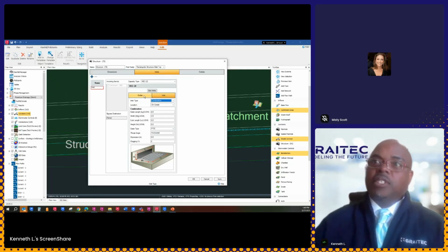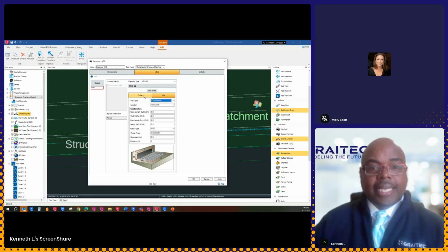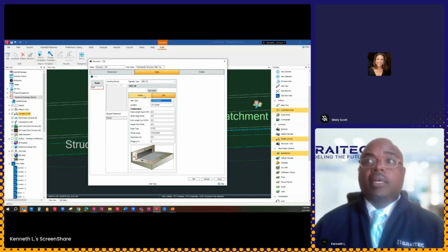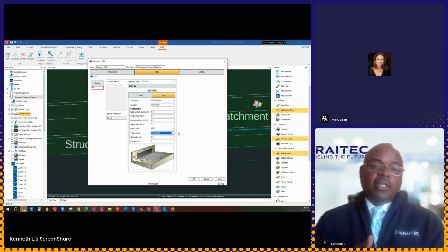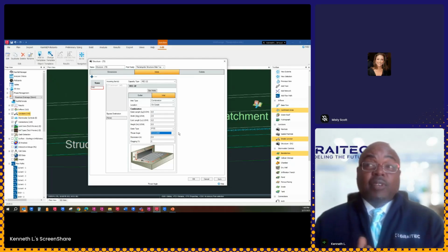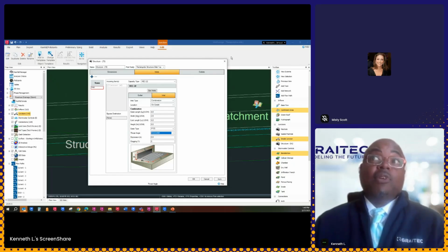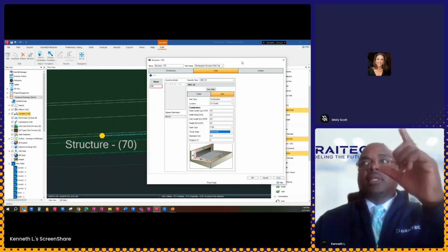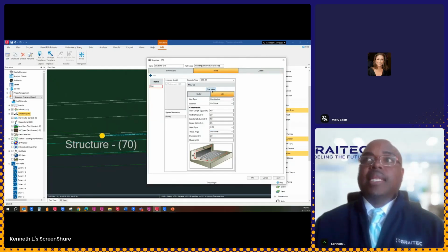We have parameters in terms of the grate length, grate width, curb length, also the height, the grate type, whether it's a throat, horizontal, incline, vertical, depression, and clog, how much and how efficient this inlet is running. If it's clogged at 50, that's not very efficient, right? But we can put in certain parameters. And once we have those parameters for our inlet, we can select size inlet.